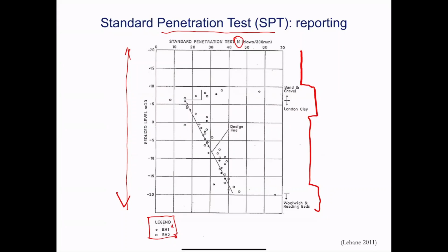And if you plot all the data here, you can actually do something that's very common in geotechnical engineering, which is getting a strength envelope, right? Why do we want a strength envelope? Well, let's say you get some relationship here, y = mx + b for a linear relationship. Then let's say you're running classes. If you want to tell classes that your soil strength will increase with depth, then you can plug in a linear relationship, right? Or you can also say we have a uniform strength for this homogeneous layer, right? But normally we would consider the effects of strength increase with depth. And you can characterize the different types of soil type. That's how SPT data may be reported in some logs.